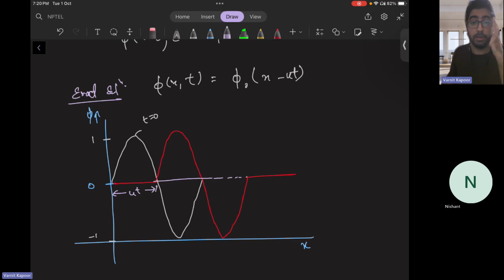Similarly, if it's a pulse wave, it will also shift accordingly for a linear wave equation. So you can evaluate the discretization schemes using UDS and CDS, whether they can predict the shift without introducing diffusion, where smearing is happening, or dispersion, where wiggles are happening or not. So far, we have seen numerical diffusion and dispersion and the unsteady convection equation.